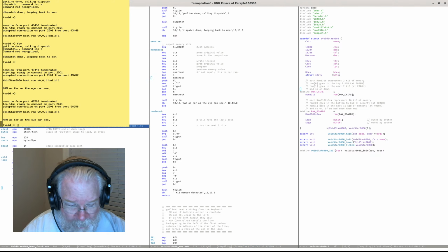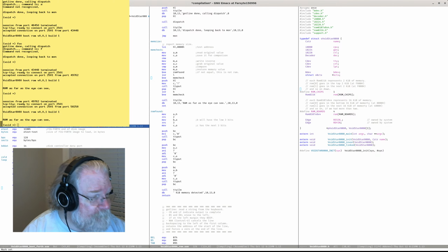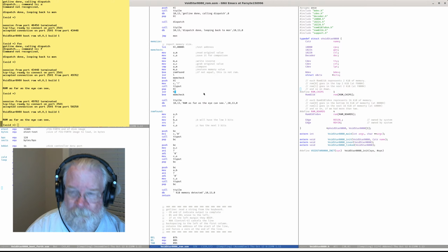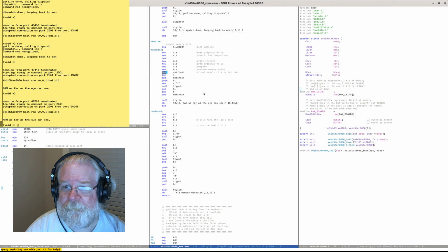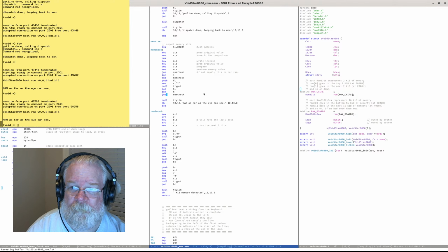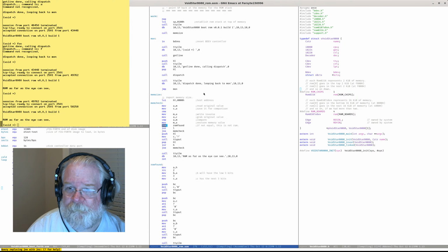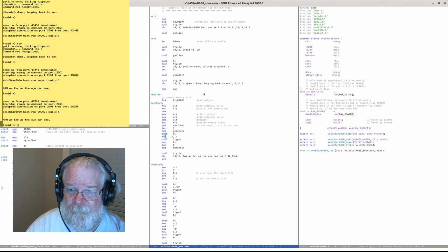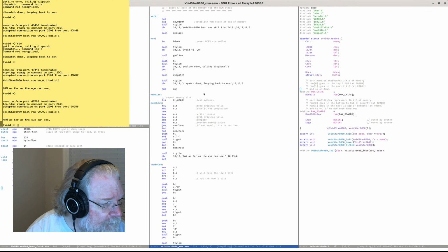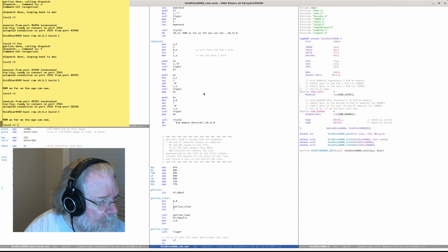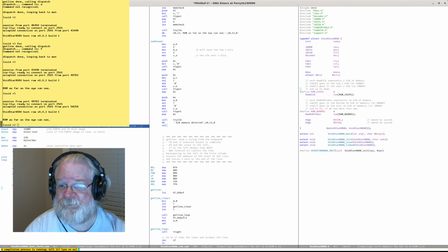Yeah, so my compilation here is not including error messages from the assembler. And 116, this is an MVI into C. And 156 is a RET. And now we are assembling without errors.